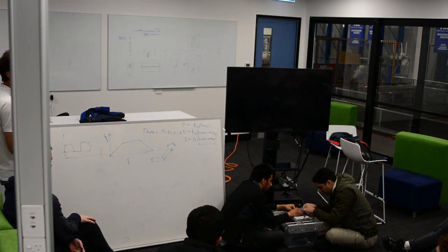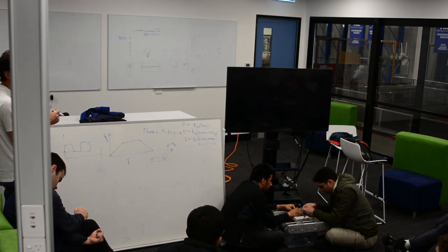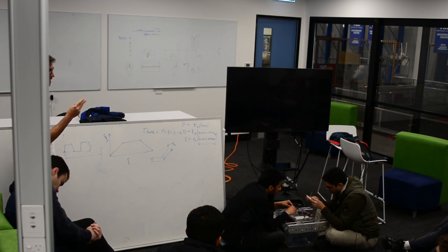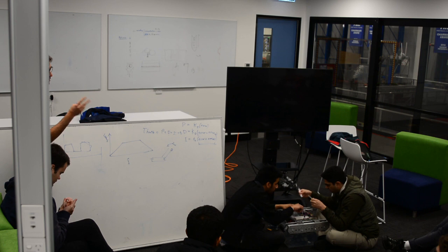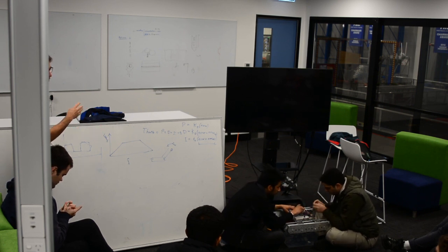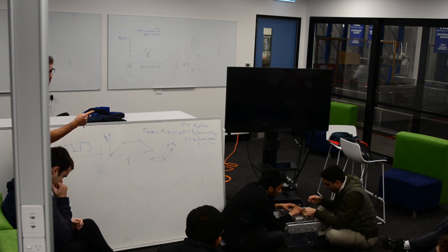Then you get twice the precision, because you can trigger an interrupt service routine on A or B. It does mean you have 4 interrupt service routines, and your processor is gonna get interrupted twice as often. So you've gotta decide whether you need that precision, or you need the compute time to do other things. You've got that one processor.